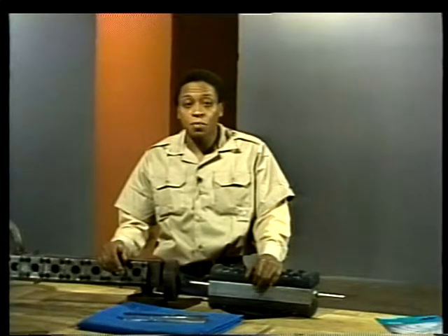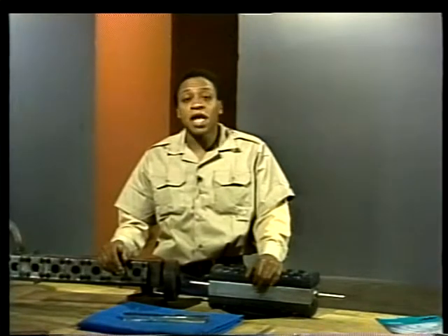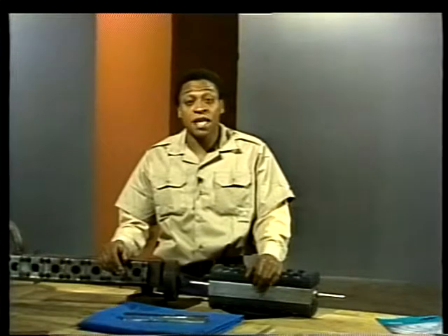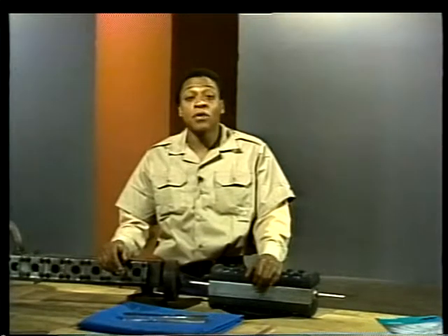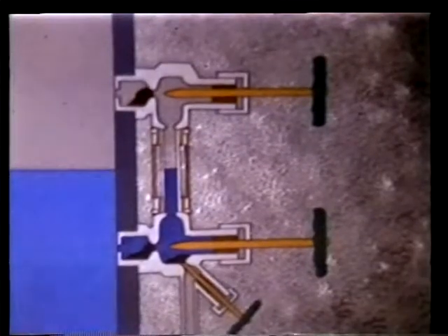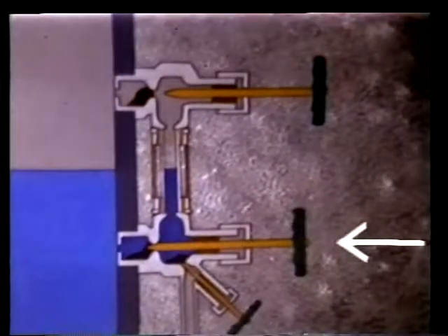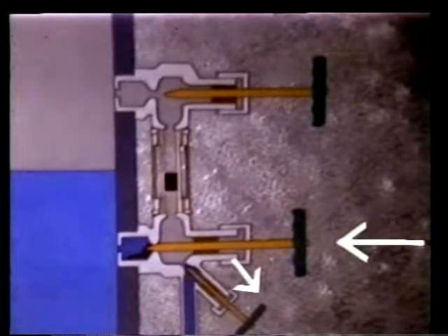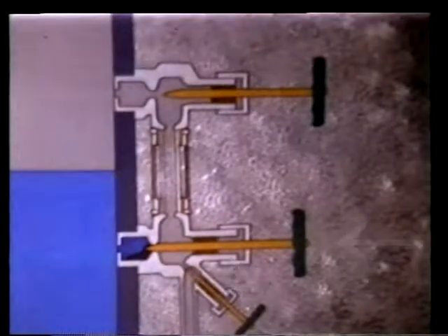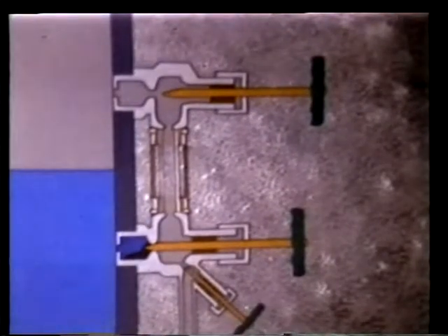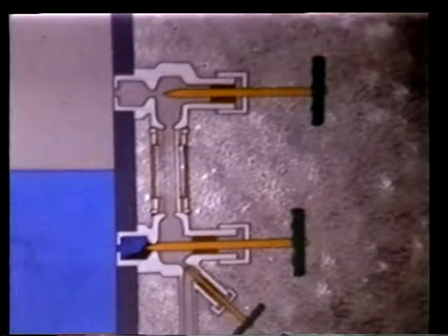Another problem, plugging, is most likely to occur at the isolation valves because the valves restrict the pipe and sediment can collect there. Blowdown usually clears up this plugging. Blowdown is started by closing the lower gauge connection and partially opening the drain valve. This allows the flow to continue until the upper gauge connection is clear. If there is free flow from the drain, the connection is open.